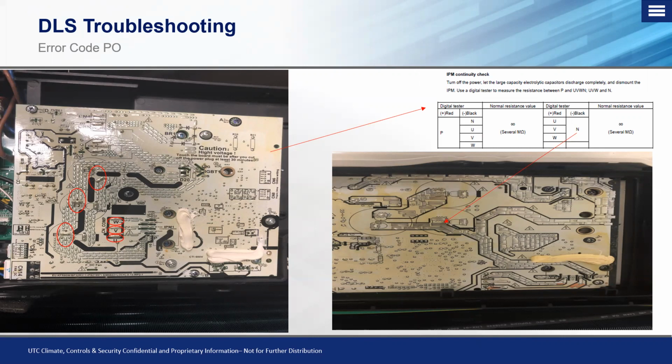Okay, but on the single zone cell boards, you'll see you still have the same setup, but it's not as straightforward as the board on the left. What we are looking for are those three little circles on the board, which are an indicator of the backside of your capacitor, E1, E2, and E3, just like we did on the left-hand side. And you'll see on here, your positive and negative posts. Okay, so that's where you want to check for that DC voltage. Same rules apply. Whatever your incoming DC voltage is, multiply that by 1.4, and that should be the DC voltage reading that you should expect across these capacitor buses.